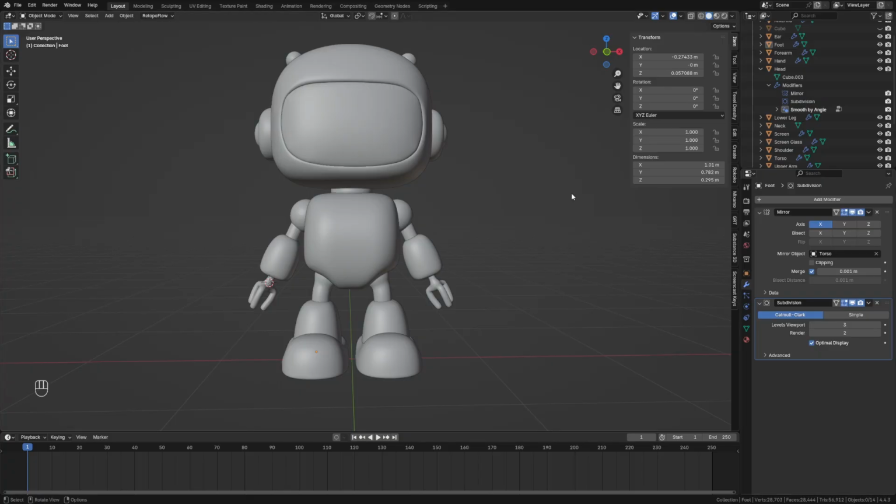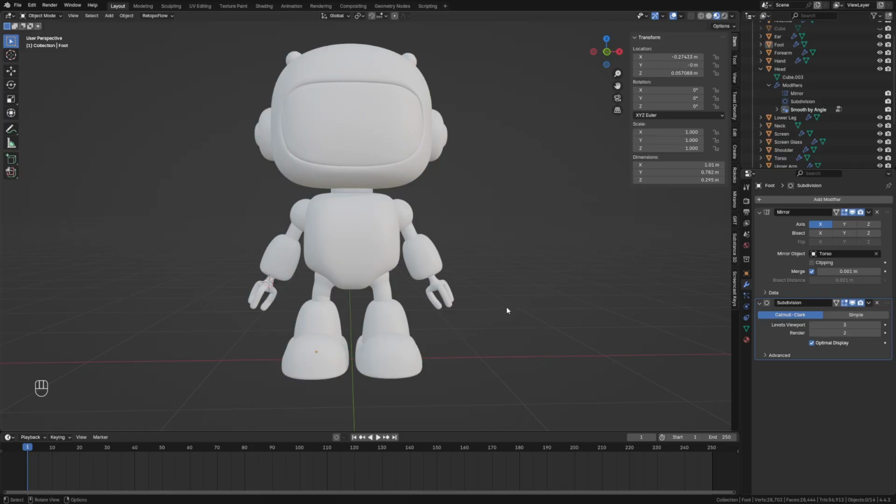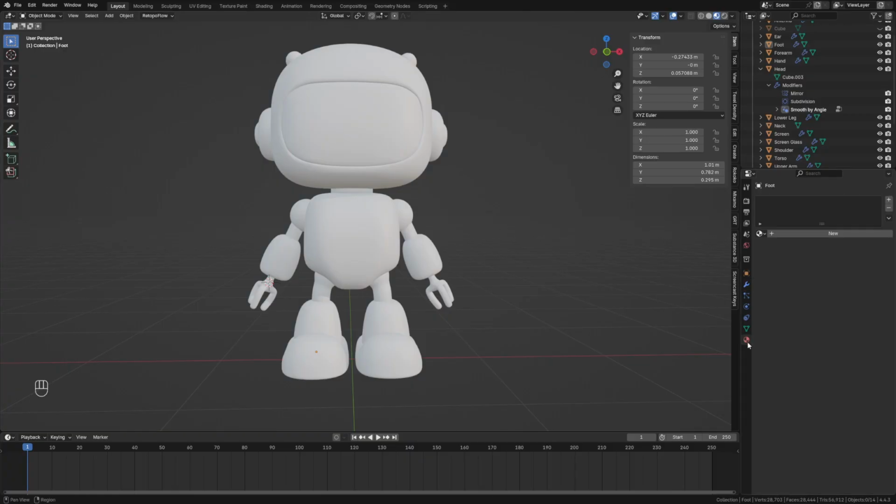In the top right corner of the 3D viewport, we can choose how objects are displayed. So far we only used solid and wireframe modes. To create and see materials, we need to switch to Material Preview mode. This mode shows the objects with their materials and basic lighting, so we can preview how it will look without rendering. In the Materials tab, we can see which materials are assigned to the selected object, change them or add new ones.